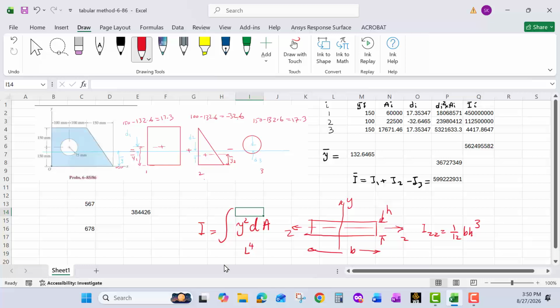One problem with that kind of calculation, even if you are referring to the table, I can use that I from the table, this one from the table, that one from the table, and combine them. But the problem is the values which I bring from the table are calculated assuming a different neutral plane.